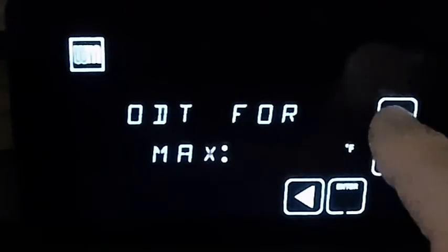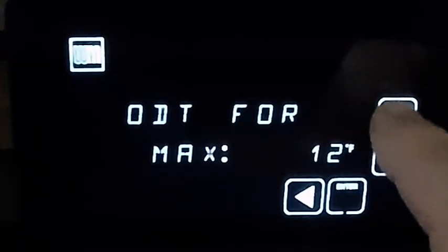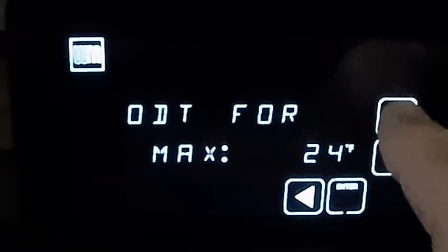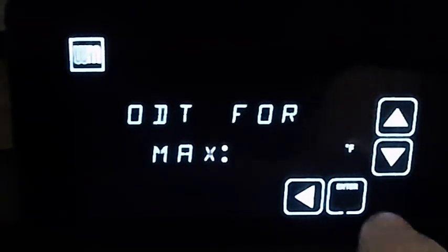This can be set anywhere between 0 and somewhere around freezing. Setting this to 32 degrees will give maximum boiler temperature when the outdoor temperature drops to freezing. Lowering this setting will increase efficiency, but may decrease the comfort level in the home. Consult your customer for their preference.